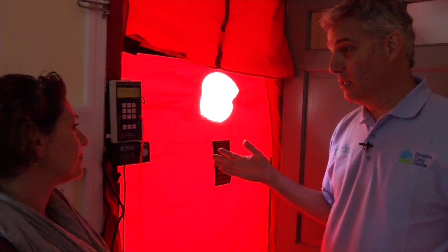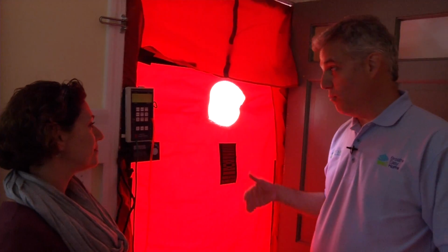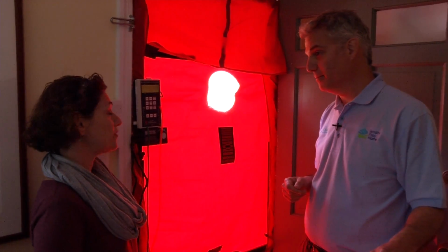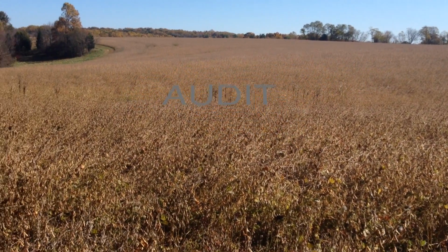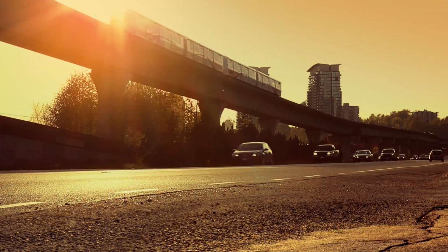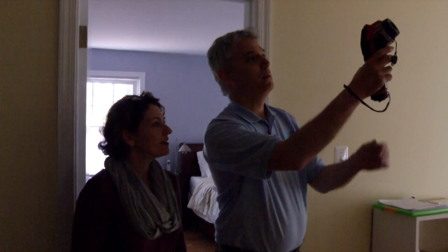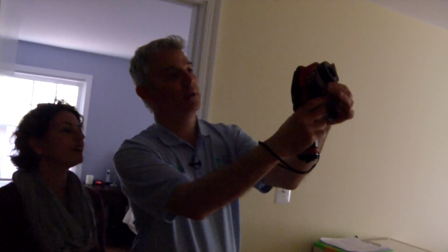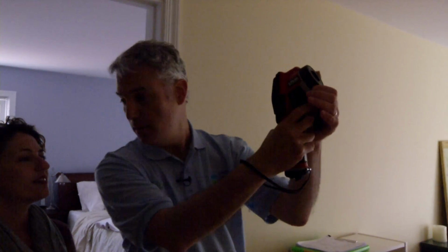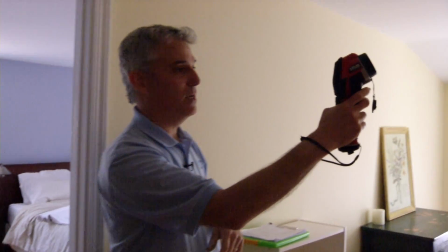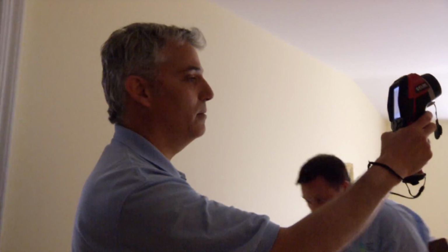Because what we normally do is we scan the house with the infrared camera before we run the blower door, and then while the blower door is running, we'll go ahead and scan the house again with the infrared camera. Terrific. So let's take a look here. I'm just going to quickly scan the house, looking at all these areas and looking for temperature differences, to see if there's anything that really sticks out.